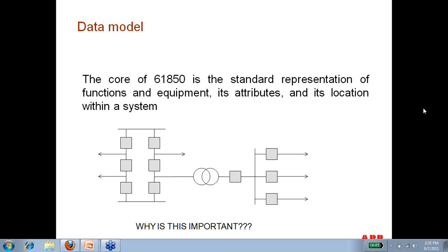When we talk about interoperability, of course, given that definition, you may have a condition where one device provides support for a particular piece of information that's optional, whereas the other device does not. But there are also, within the context of the standard, specifications that describe the capability of the devices, at which point that becomes pretty important to review as part of any 61850 substation automation system specification.